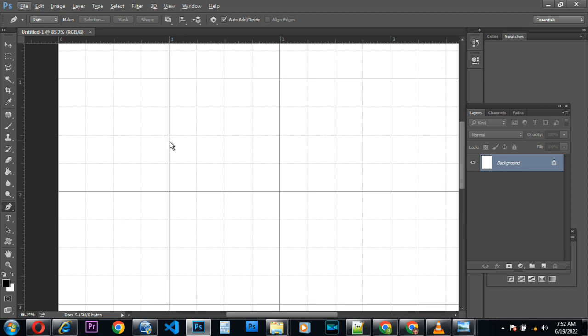So this time around, what I'm gonna do is I'll start by using my pen to draw. I'll start here, this point, then I click on this one too, I bend. Then, as you can see, this perpendicular line, I'll have to cut it off so I can continue, so that this perpendicular line will not have effect on the next line I'm going to create. So I'll hold my Alt key, then click at this center spot so that I can cut it off. Then I click. As you can see, I've removed one of the perpendicular lines.